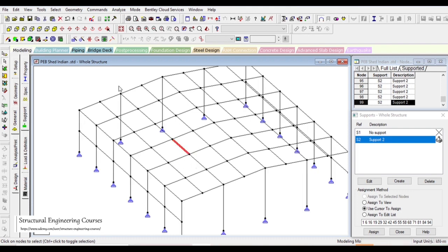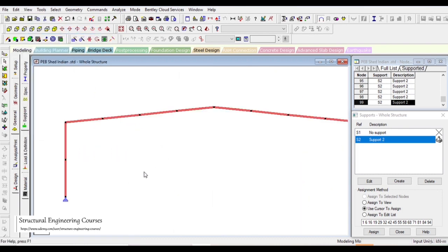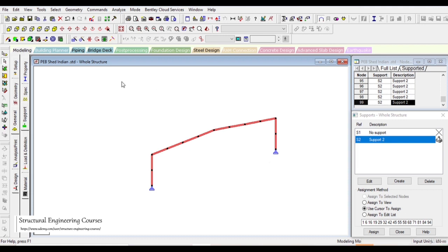That is basically the thing is that this rafter that we are talking about here is very strong along this axis, that is along x axis, but simultaneously it is very weak along this axis, and many failures have also occurred in the erection stage, that if the contractor does not brace this portal sufficiently along the perpendicular direction, then it has also happened that this whole arrangement has come down or failed along the perpendicular direction.